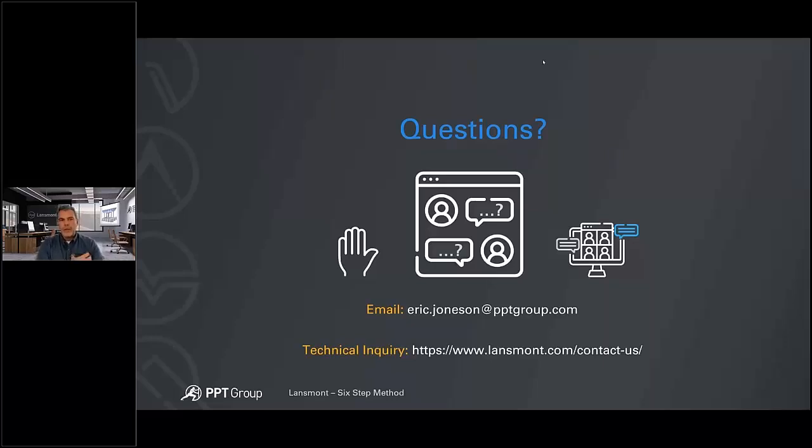That's probably a long one to answer on the phone, although I would say when I do this, we do the vector sum from the instrument itself. We use the vector sum, which means that it's critically important that when you're analyzing those events, you're analyzing the primary impact pulse. And it's also important, if you're looking to do equivalent free fall drop height studies from the field, that you first calibrate whatever the system is that you're going to send out into the field to do the data collection itself.